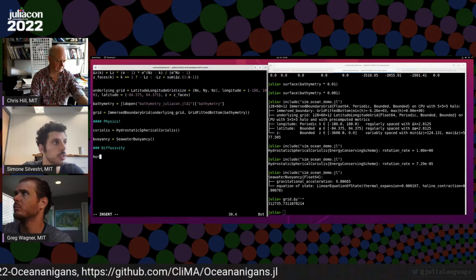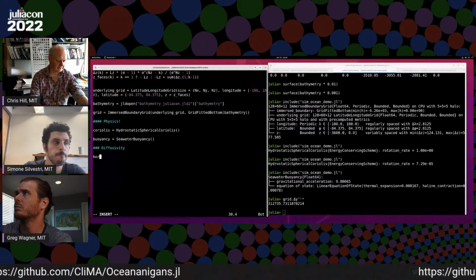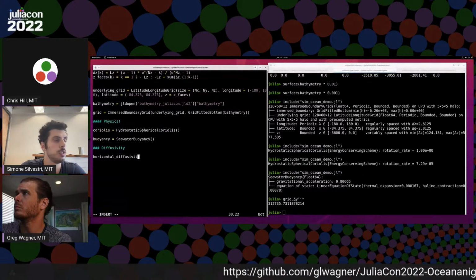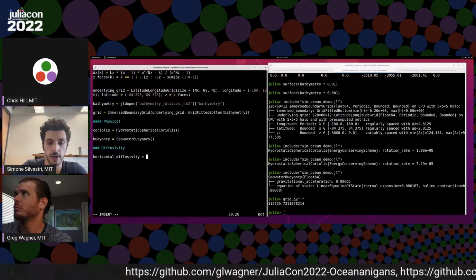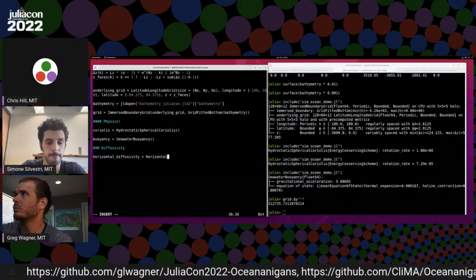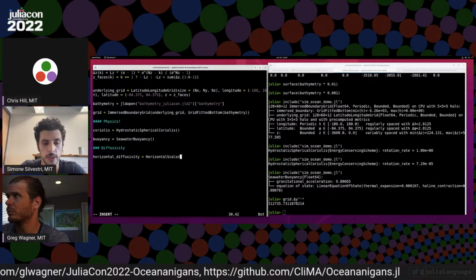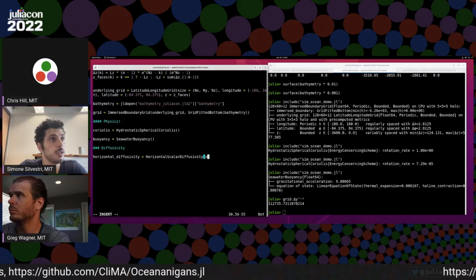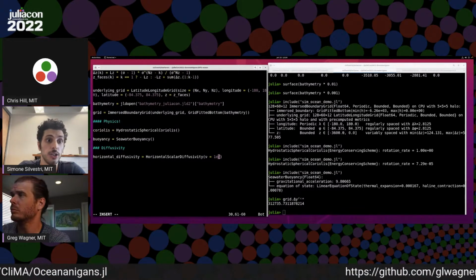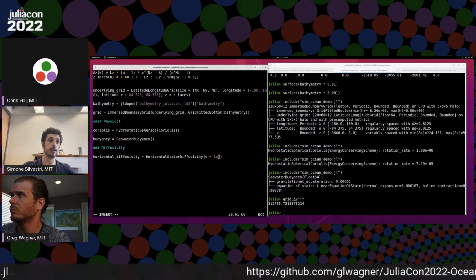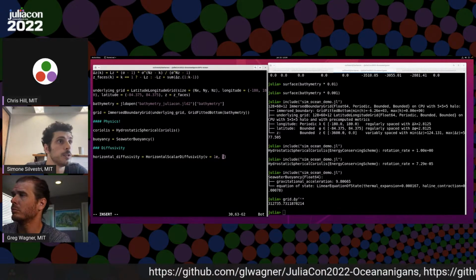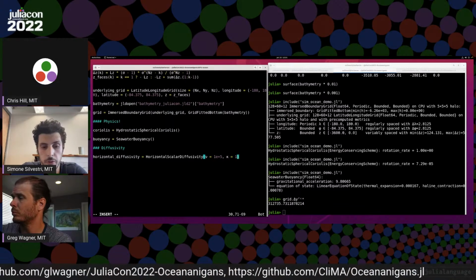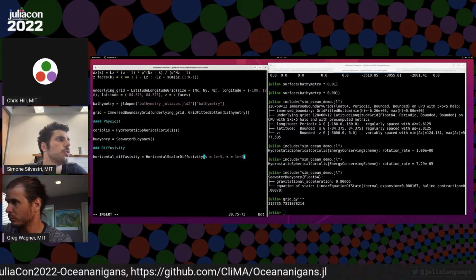So for horizontal diffusivity, we can specify horizontal scalar diffusivity with a viscosity. We have to keep it quite large here because, as I said, there are 300 kilometers that we have to cover. So 1 times 10 to the power 5 is a good value for the viscosity, and a diffusivity of 1 times 10 to the power 2 is also a good value here.